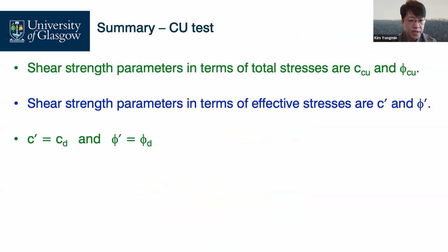So we can get certain shear strength parameters in terms of total stress and in terms of effective stress. Once you obtain this, we need to determine which parameters can be used in our design. It depends on you, on your engineering judgment.